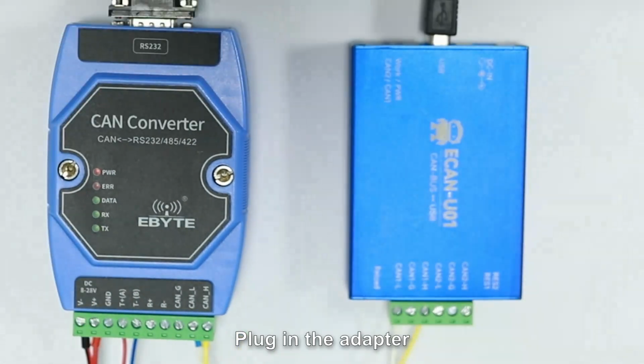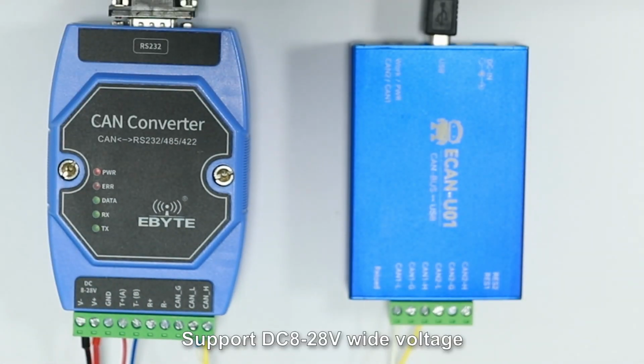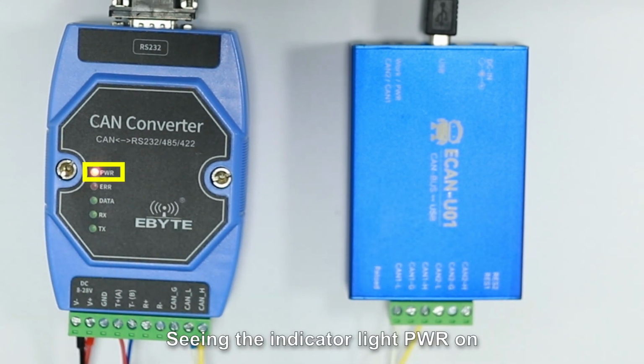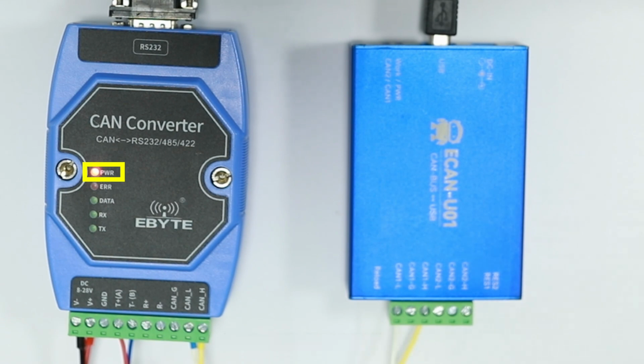Check the circuit after connecting. Plug in the adapter. It supports DC 8-28V wide voltage. You will see the indicator light PWR on, showing startup was successful.